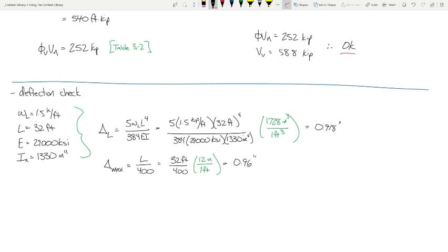Is this beam sufficient? What is the performance ratio under deflection? 0.956. What's interesting is, out of moment, shear and deflection, what is actually the most important limit for this beam? What's actually governing the design? Deflection. So this beam has oodles and oodles of capacity, and we actually had to make it bigger just to make sure it doesn't deflect too much. It's very interesting how service limit states might end up actually governing your design.